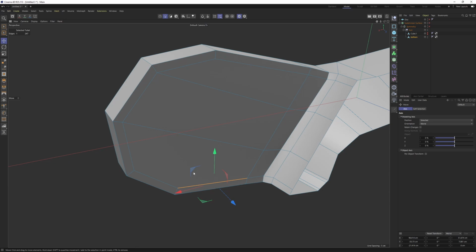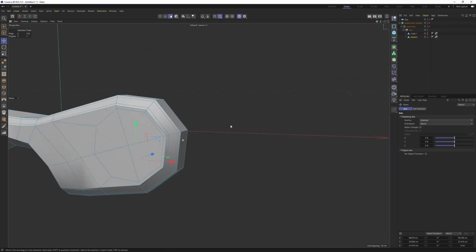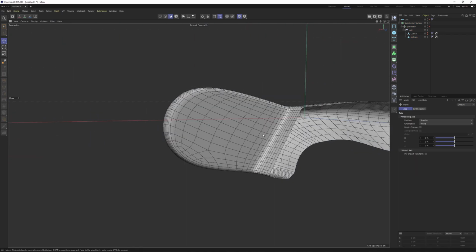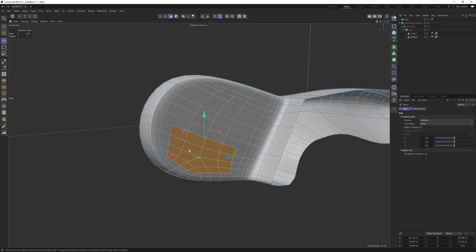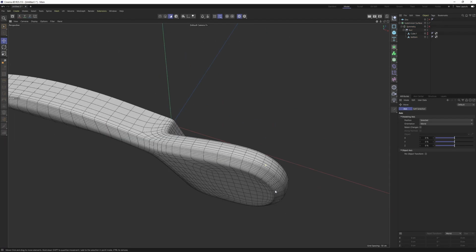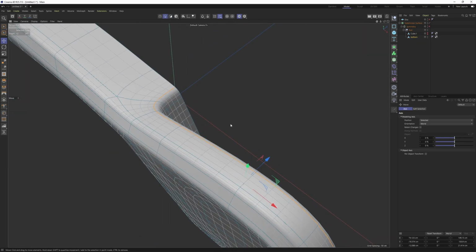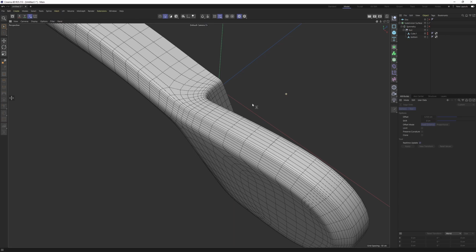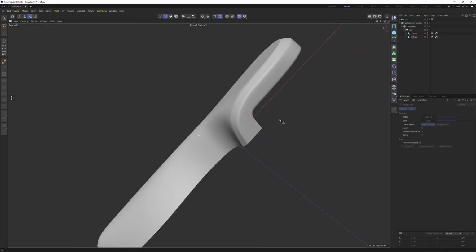Now we have one hang-on, but I will not touch that. You can see if I enable Subdivision Surface, it's going to handle that easily. We will need an extra supporting edge on here, because we want something sharper. Press Ctrl, extrude, press Q. Now this is looking much better.